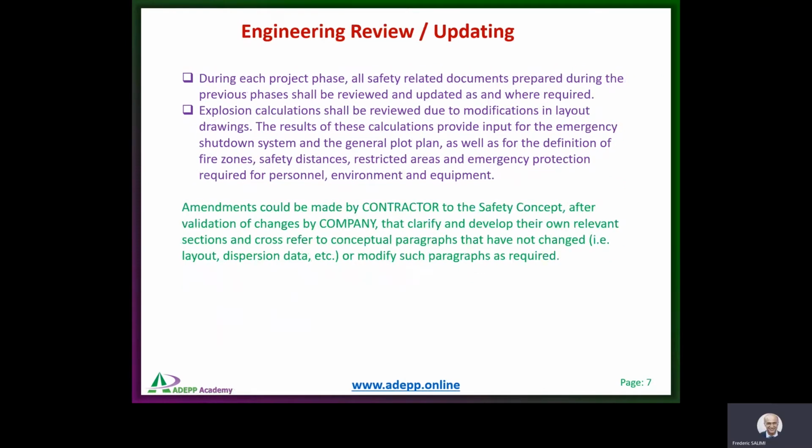About engineering review and update. In fact, during the project phase, all safety-related documents prepared during the previous phase shall be reviewed and updated where required. For example, if you wrote a safety concept at FEED stage of the project, at the beginning of detailed design you have to write the safety concept, what is the philosophy, and I will give you the content later. It should be modified and go for the detailed EPC phase safety concept.